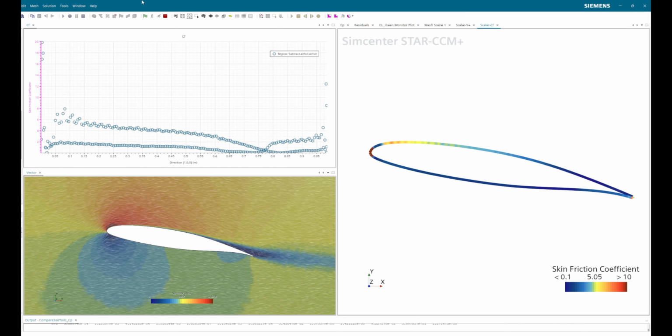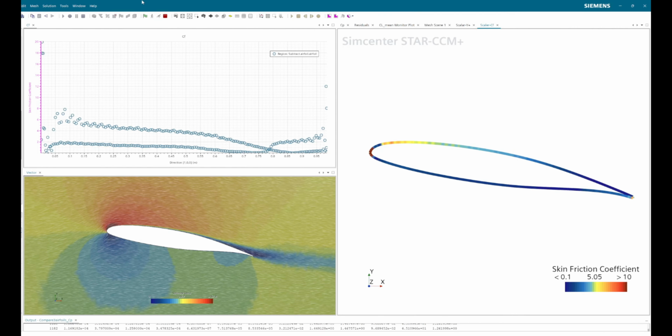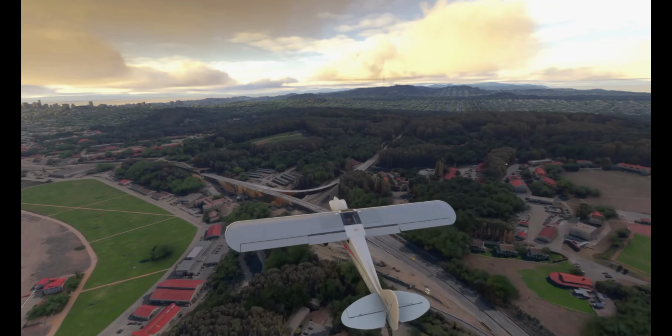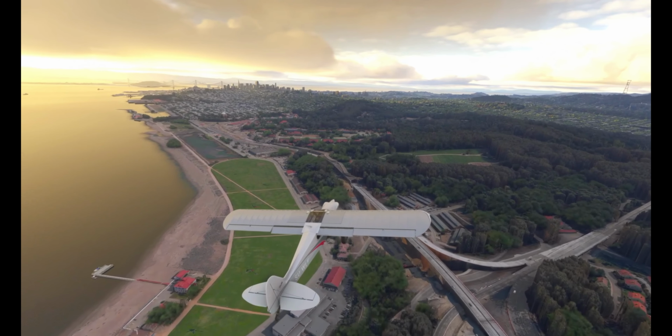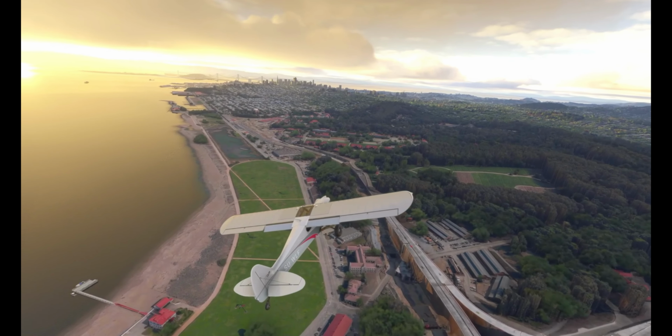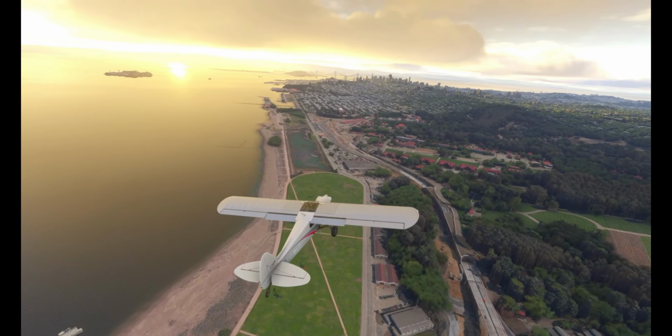A larger CF means a steeper velocity gradient, while a CF close to zero indicates either a nearly uniform laminar flow or a turbulent region with almost no velocity gradient. By combining the analysis of Y plus and CF, we can assess the accuracy and validity of the simulation model. This allows us to clearly visualize the flow details and quantify aerodynamic losses more precisely.